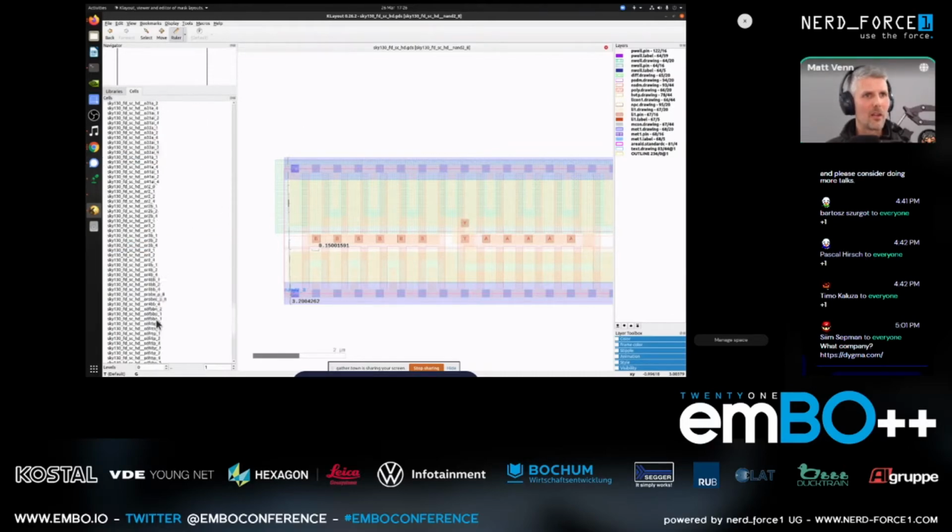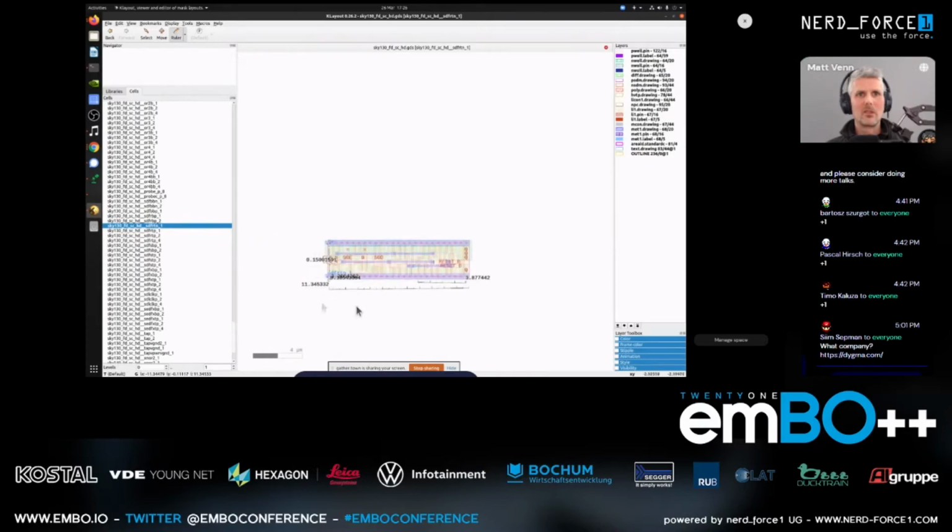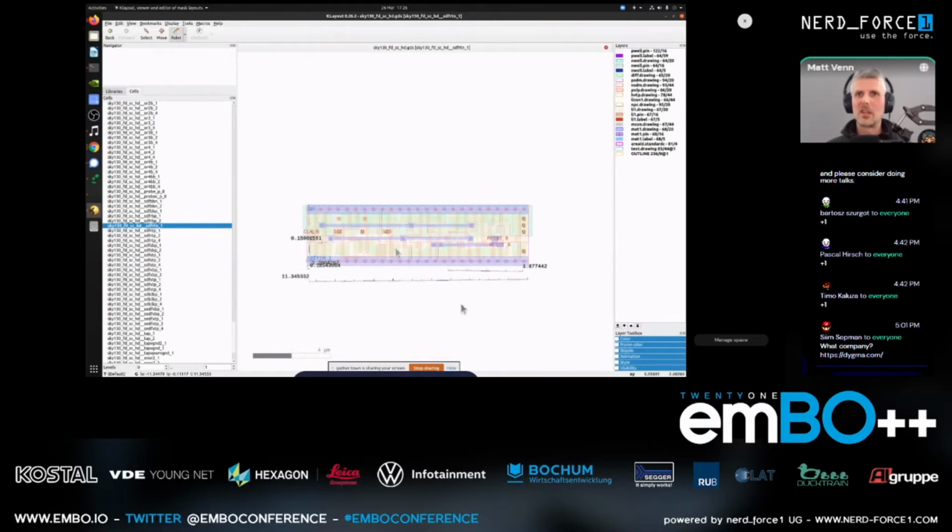And just one other thing that I think is quite interesting is, memory is a completely different kettle of fish. And the reason why memory is so optimized is because this is the size of a flip-flop. So it's absolutely huge compared to an inverter. The inverter was about this wide, 1.2 microns, and this is off the screen, it's so wide, 11 microns. So they're very inefficient in terms of space. So that's why we have DRAM, which is operating in a completely different way and is much more complicated, but much, much more optimized for area.